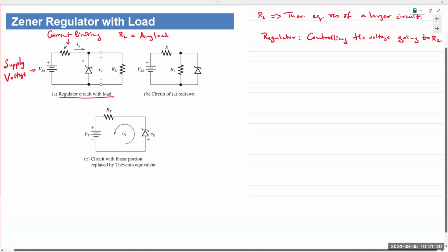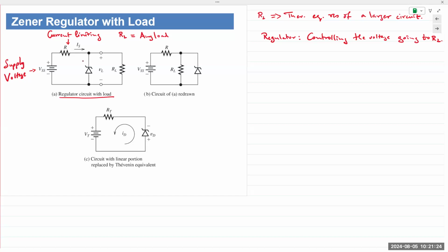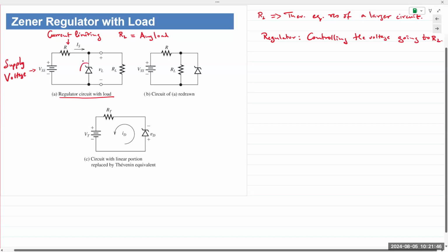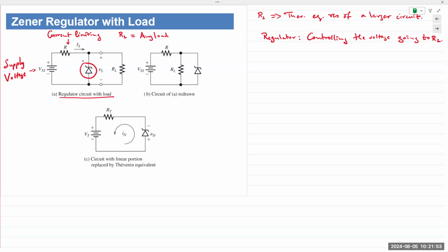Second thing is all of the circuit analysis remains the same from 201. The only thing that has changed are the components we are using, meaning the diodes in this case, then the transistors going forward. So we had diode circuits in the first half of this chapter, p-n junction diode. Now we have Zener diodes. The analysis we perform, these equations that we use, they're still exactly the same. The only thing we need to do is remove the nonlinear component from the circuit and analyze the rest of the circuit without it.